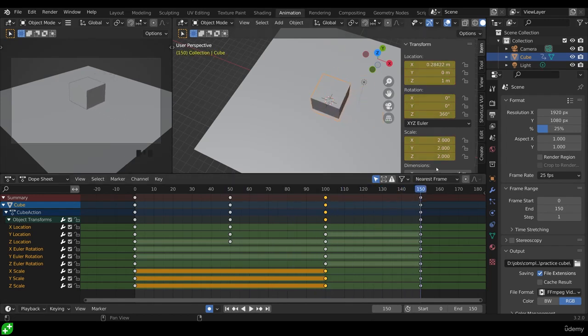to twice as big. So as well as creating keyframes by recording, we can also press Shift D to duplicate keyframes. This is particularly useful if you have a set of channels such as the scale here and you want it to stay the same, so keep the same scale across this area. You can duplicate this keyframe to the endpoint that you want and it will stay the same in this area.